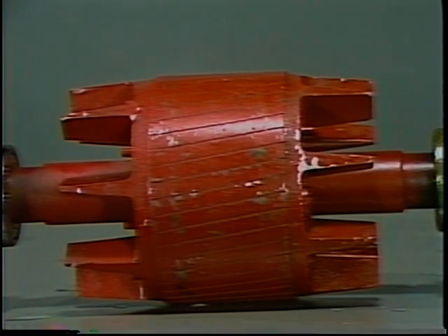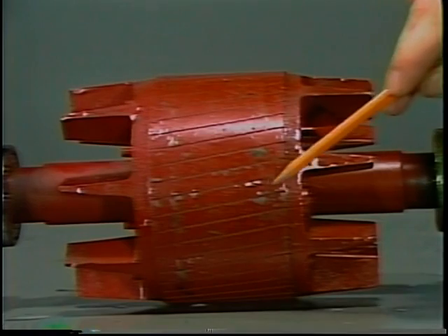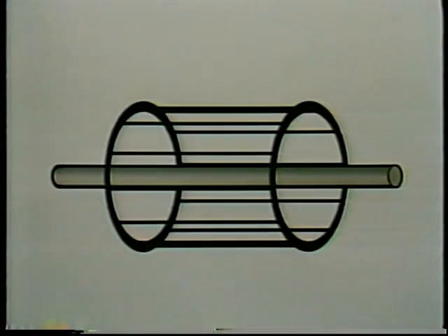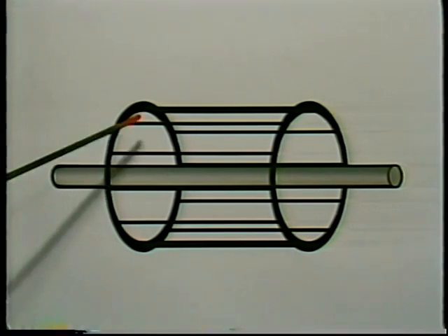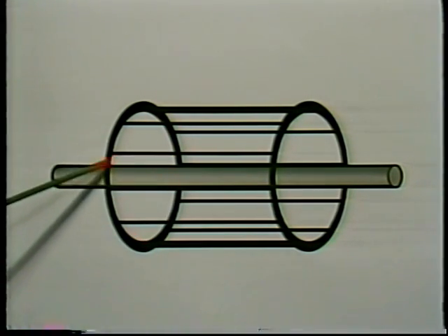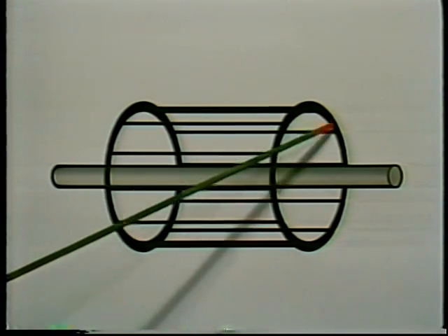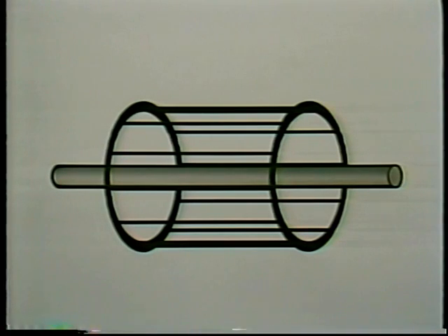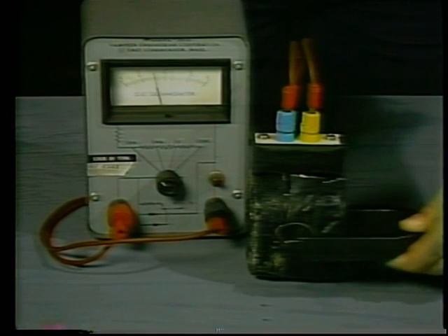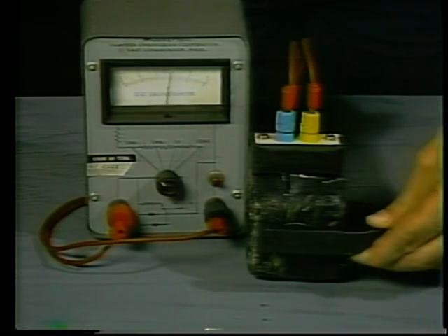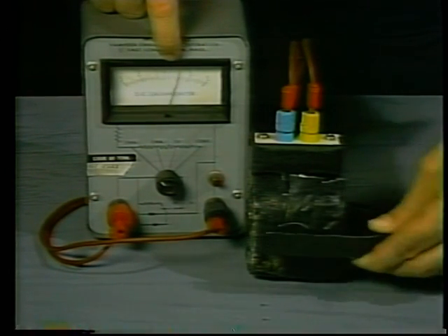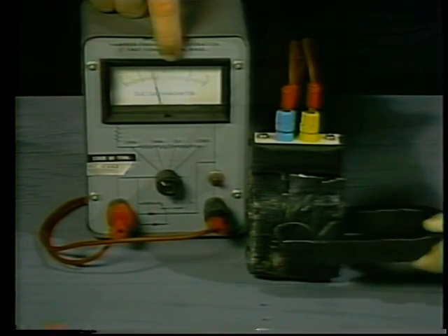If you could look inside the iron core, you would see that the rings are connected by solid bars through holes in the core. The bars and the end rings form a conductive cage, often called a squirrel cage. The cage is often cast in place, though sometimes it is assembled from separate copper bars and rings. Now, anytime lines of magnetic flux move through a conductor, voltage is induced in the conductor. The more lines, and the faster they move, the higher the induced voltage.